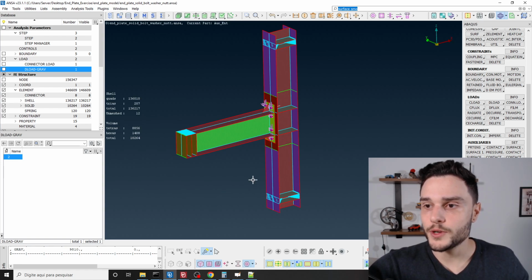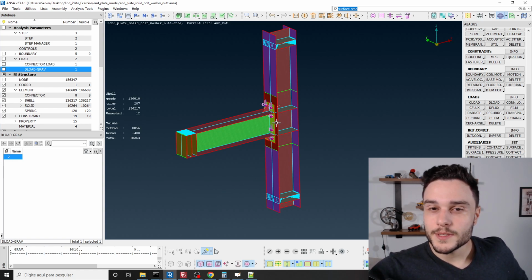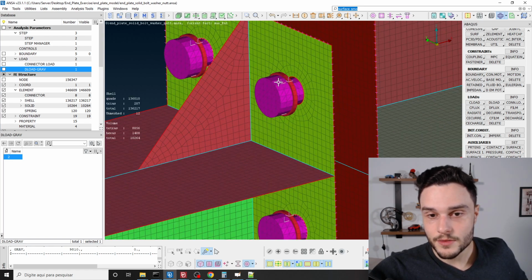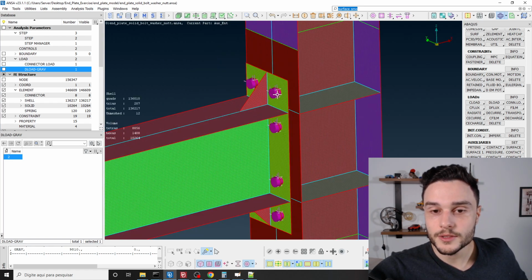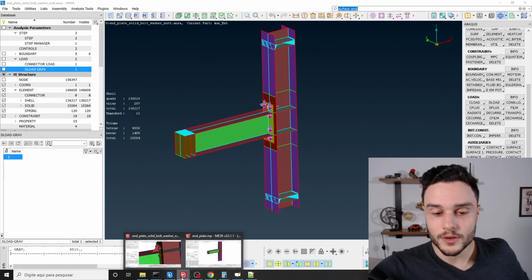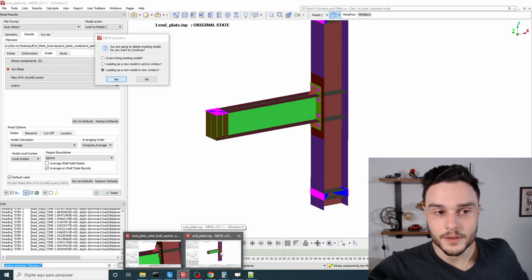All right, I'm pretty happy, guys, because I end up teaching so much about so many things here about surfaces moving, node to surface contact, finite sliding, small sliding, these springs to stabilize the model. We have used many advanced tools here for nonlinear FEA.